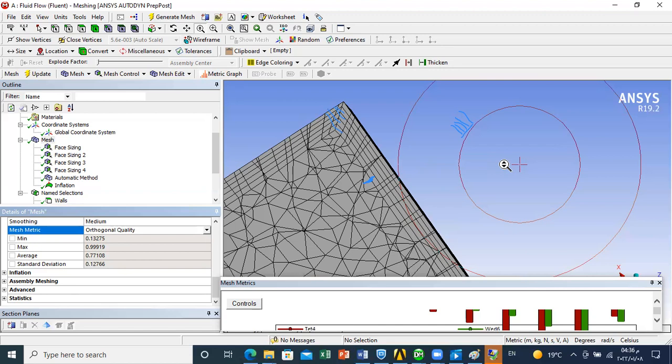Okay. Especially, for example, if you want to study a displacement ventilation room, where you introduce the flow from the lower level, you should change your inlet location. Here we considered a mixed ventilation room. We place inlet and outlet at the top. In case you want to study a displacement ventilation room, you should have the inlet at the bottom and the outlet at the top. In displacement ventilation, you rely a lot on buoyancy effects. So formation of thermal plumes is of high importance, and it's good to have inflation to trap these boundary layers. Okay, so this is for different strategies of meshing.